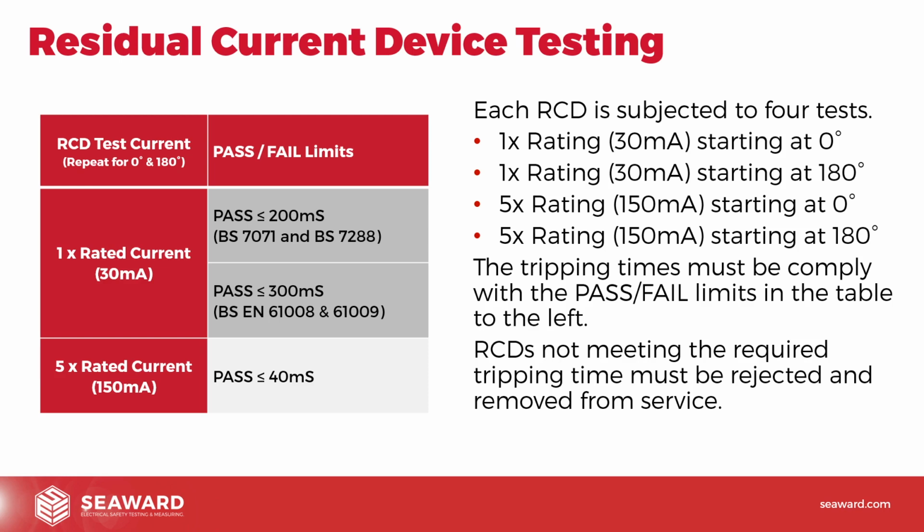We want to know that this thing's going to operate when we have a fault, not 3 times after we've had the fault. If you have the fault 3 times, it starts to work, then it comes back in. We need to know it's going to work straight out of the gate every time. So when you are doing these tests, if you do notice that it fails a bit and then you retest it, it seems like it's all right, just bear that in mind, because it might be worth actually failing the item at that point, and that might be telling you that the thing's actually worn out, shall we say, or gummed up or corroded or whatever. So again, that's the test we carry out.